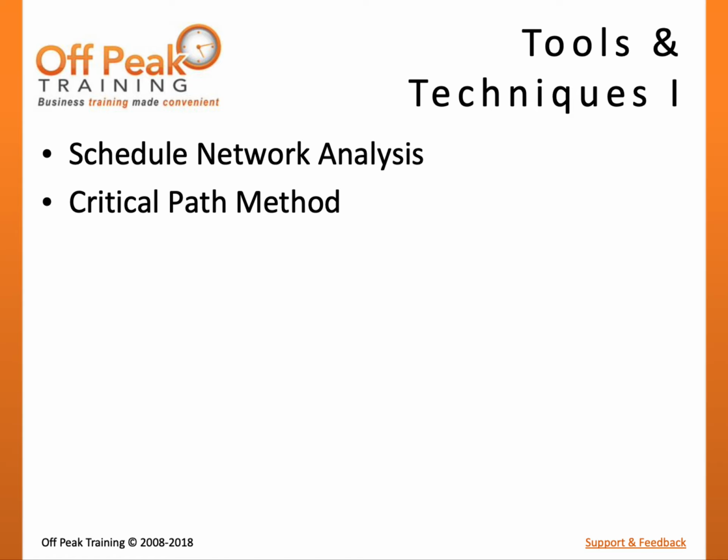Critical path method, or CPM, is a technique that evaluates schedule start and finish information and the logical dependencies to determine the longest path of required schedule activities. Because the project cannot complete any faster than this path, it helps determine the shortest possible schedule. We will explore the procedure for performing critical path method in a separate module.